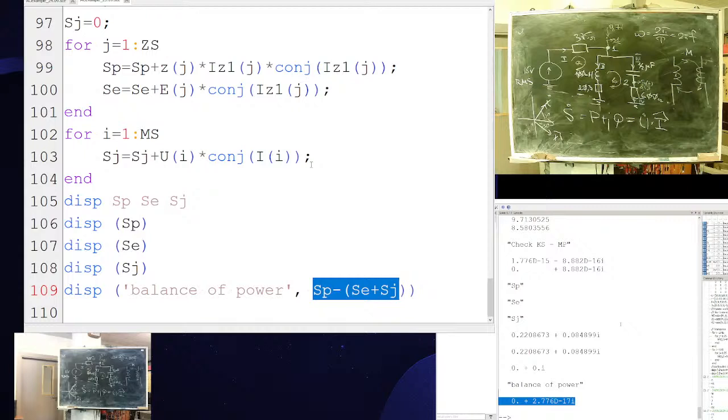If I put all to 10, its self-inductance will be 1 Henry. Here I have mutual inductance of 1/10 of a Henry. This means that if I put 1 amp at the primary side, at the secondary side I will have 1/10 of a volt.